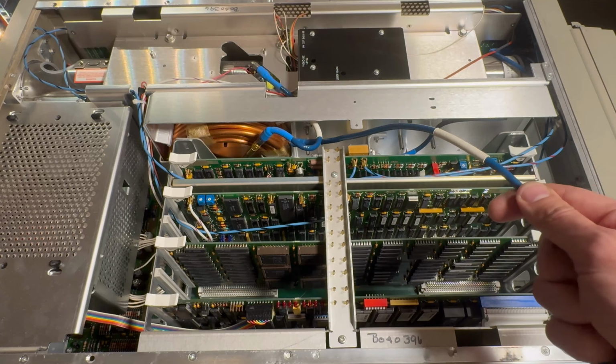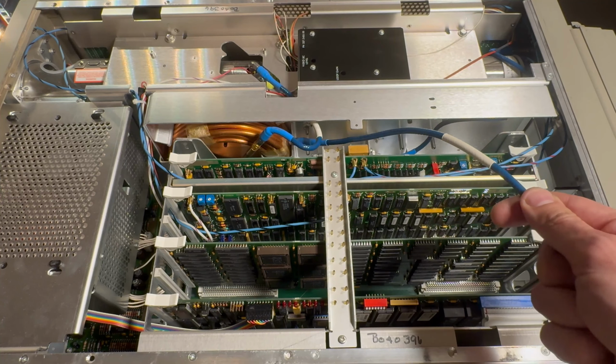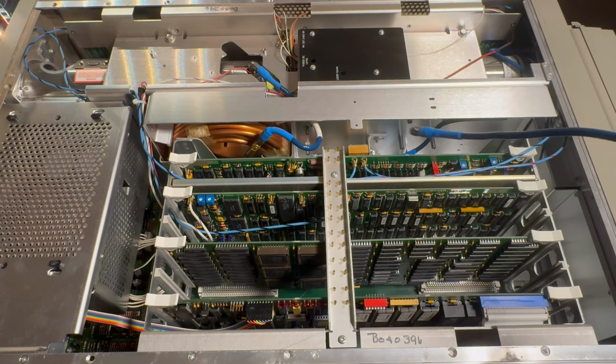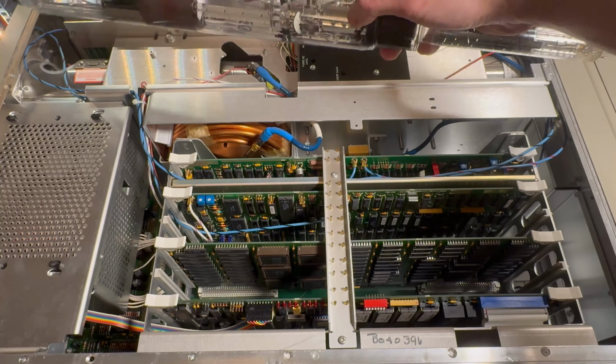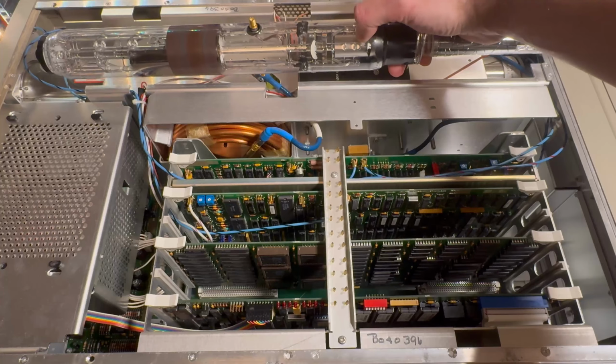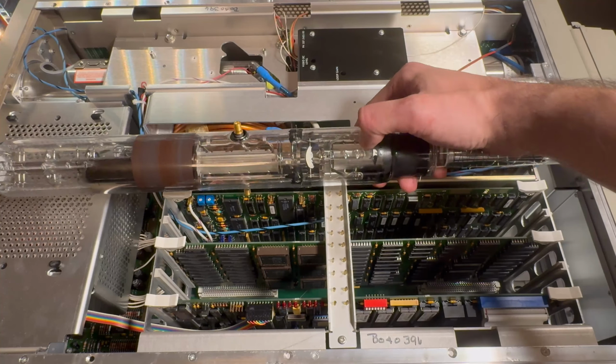These two bits here, so this trigger pickoff and this delay line, are option 1P, which is the external trigger. If you want to get one of these for yourself, first of all, why? And second of all, make sure it has the internal trigger option, because you can always bypass it and get a full 5 gigahertz of bandwidth if you desire it. But if you don't, you're gonna get a more usable instrument which has an internal trigger. And the scan converter sits inside of here, sort of like this. You can see it takes up all of the length of the instrument.